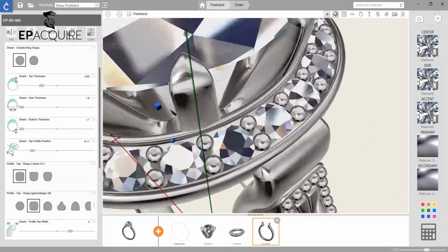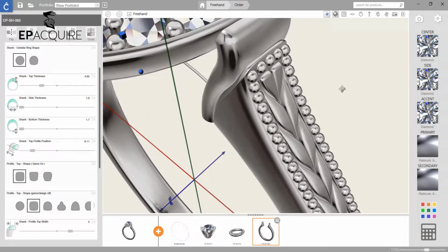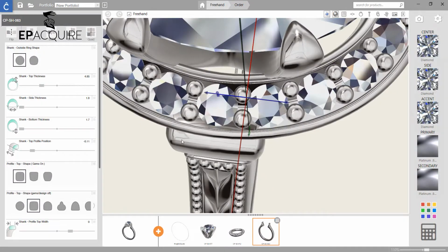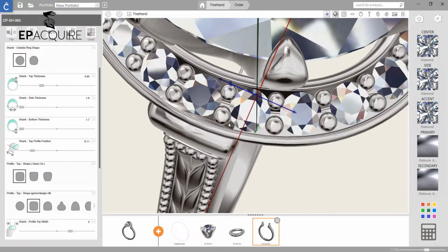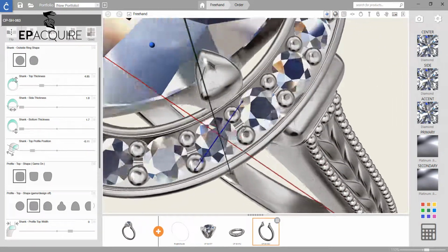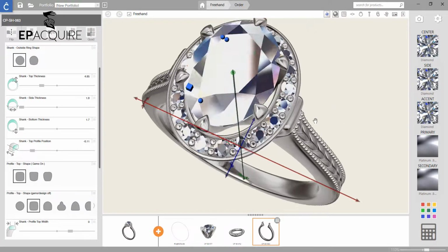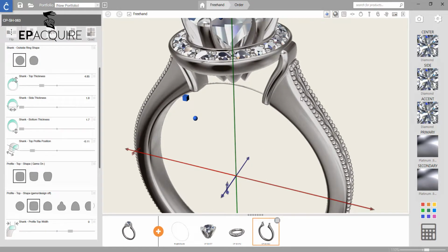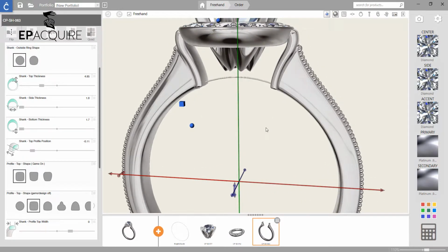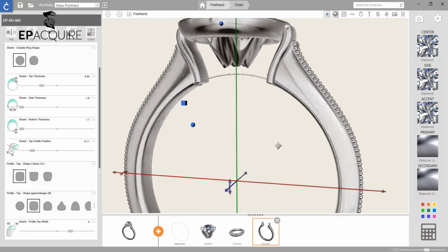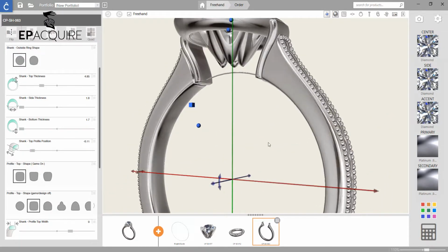Just checking that, making sure that I'm happy with where that's all sitting. You can see that this part here, that part there, is intersecting into the halo a little bit, and it might need to be adjusted slightly outside of CounterSketch. I would probably recommend Boolean differencing the halo from these rail sections so it's a nice clean cut, particularly if this is going to be in two pieces. But that's something for manufacturing purposes, since you can't Boolean difference or union or intersect within CounterSketch International.